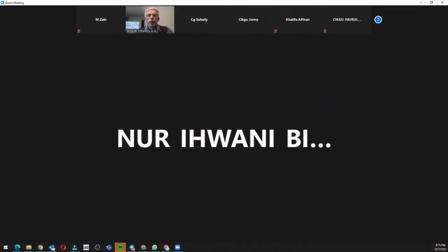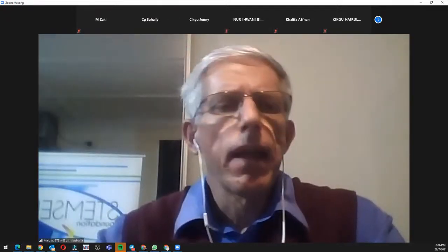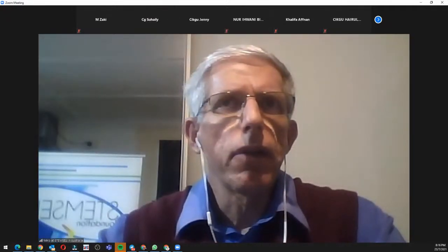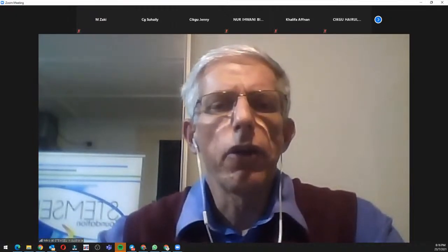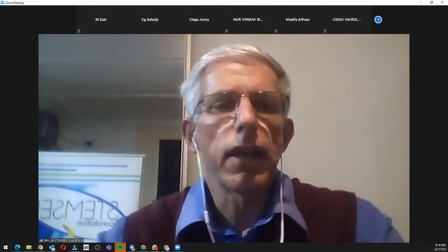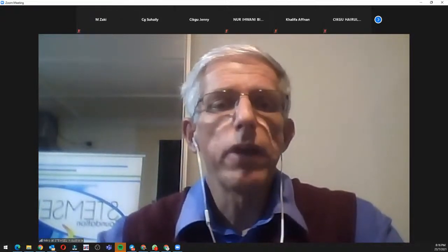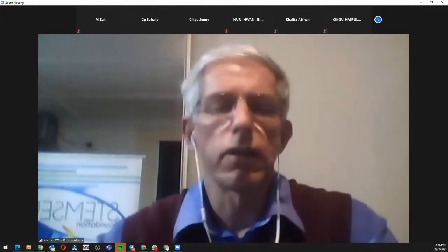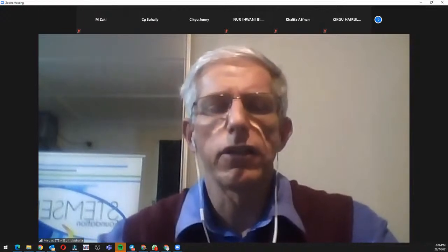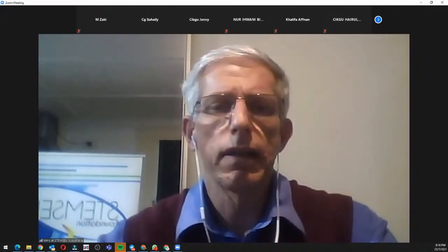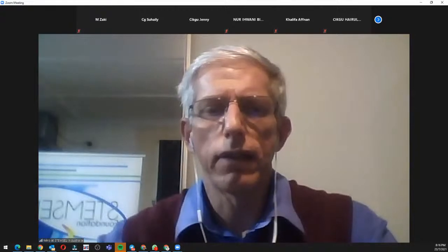Myro, I have a question. Why don't we need to put a timer for the red color? Okay, because there is the green first, and then there is a delay, and then there is the yellow, and then there is a delay, and after that yellow, the red will turn on. And that red will stay on until the repeat function actually happens. So that's why there's no delay after that, because the delay is actually until the repeat starts again with the green. That is how it works.